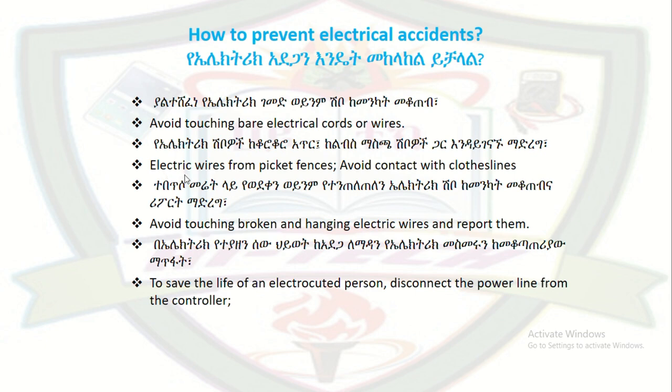Second, keep electrical wire away from the picket fence, and avoid contact with closed lines. The other one: avoid touching broken and hanging electrical wire and report them.